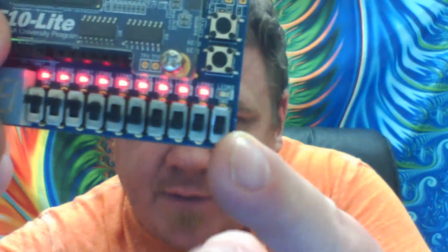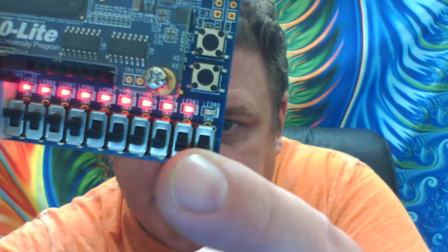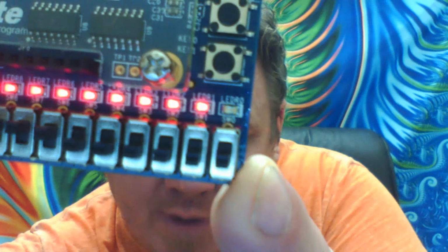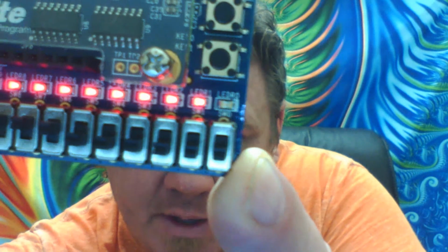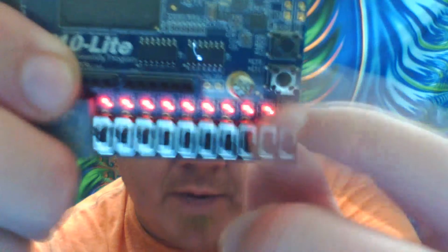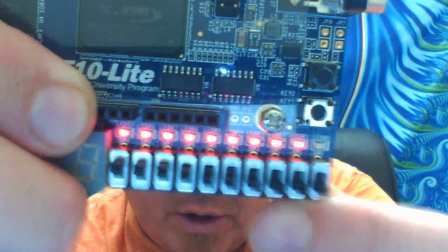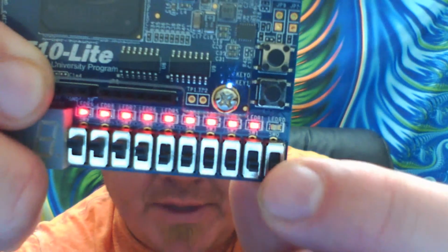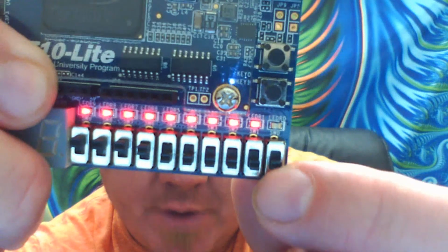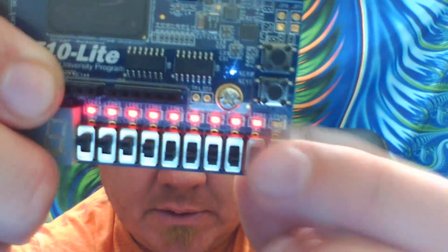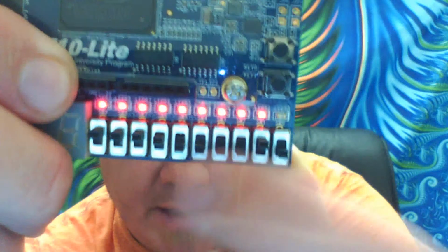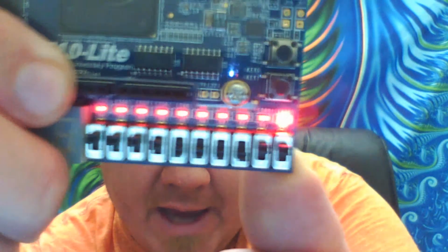Now notice, we wrote to the very first LED on there, and we're using the very first two selector switches. You can see there it's actually calling it LED R0 and switch 0, switch 1, switch 2. So right now, remember, I'm running an AND gate, and both of those selector switches are low. I'm going to run through the different possibilities. We already see what happens with 0, 0. Here is 1, 0. There's 0, 1, still nothing. But then when I do both of them high, that LED turns on.